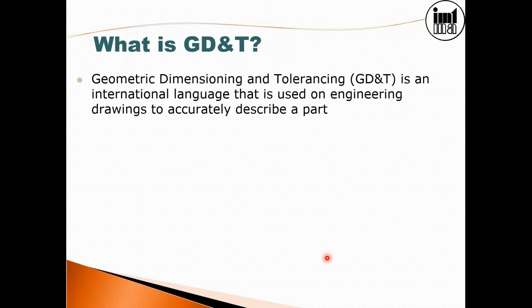If you want the manufacturing person to think what the designer thinks as a concept, then all the information in the mind of a design engineer should be transferred onto the sheet of paper. If some shaft is not to be bent, I have to tell it should not bend beyond this point. Or if one surface is perpendicular to the other surface, we should be able to tell that this should be perpendicular within the specified values.